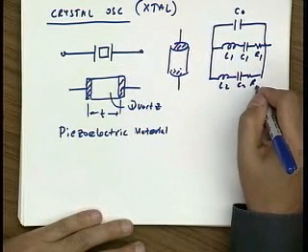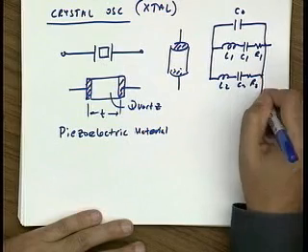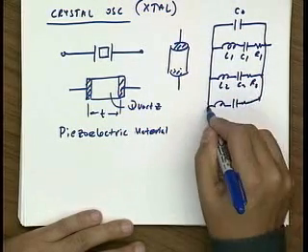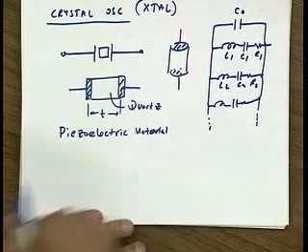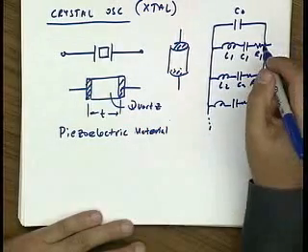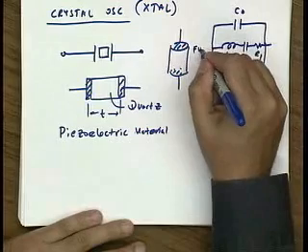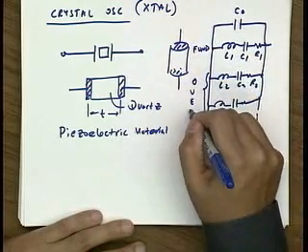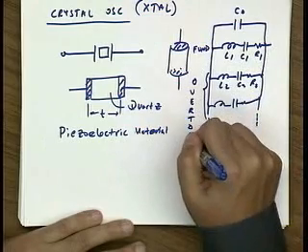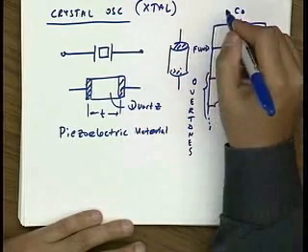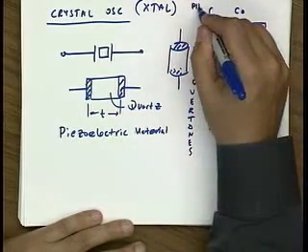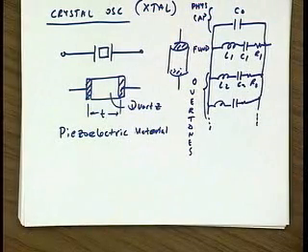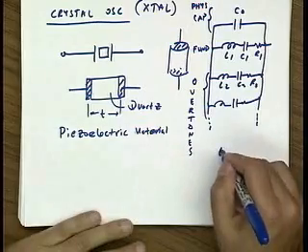So this might be L2, C2, R2, which is the first overtone, maybe another overtone, and in fact there are an infinite number of overtones. Usually we're concerned with the fundamental mode. These are the overtones. And this is actually a physical capacitor, as we talked about. Okay, so this is the equivalent circuit.